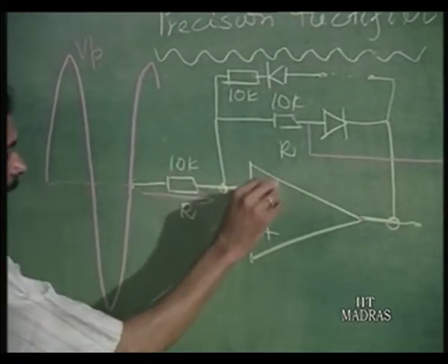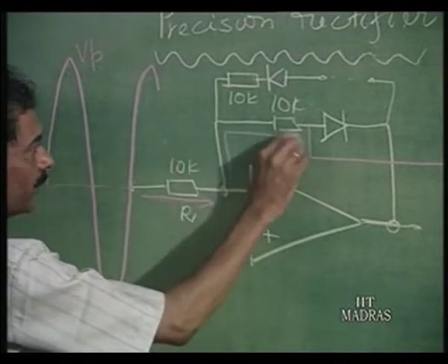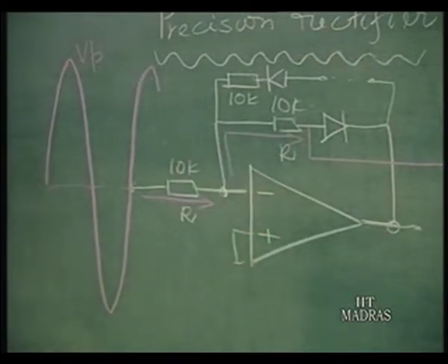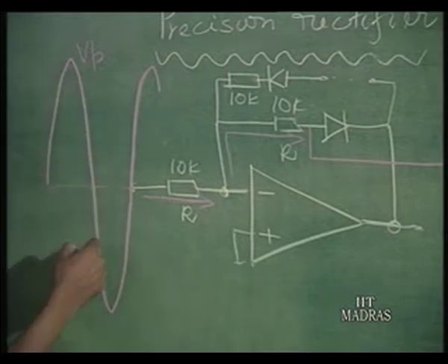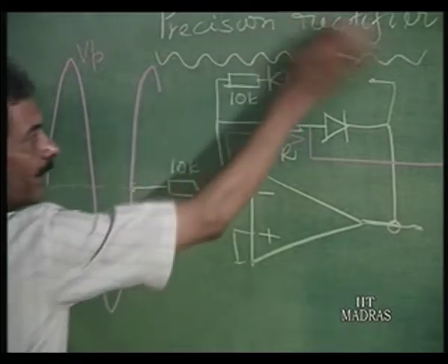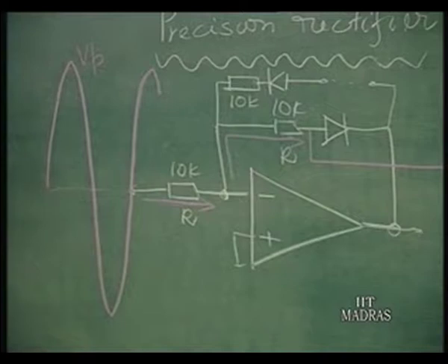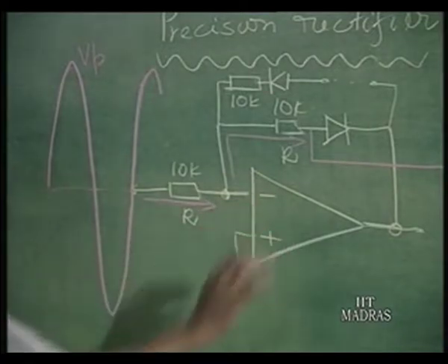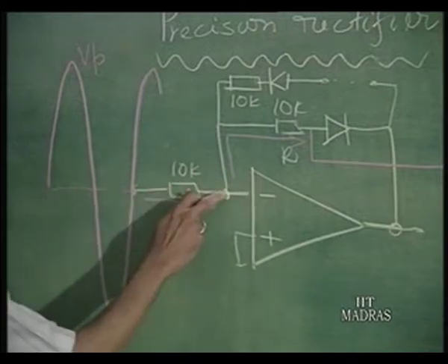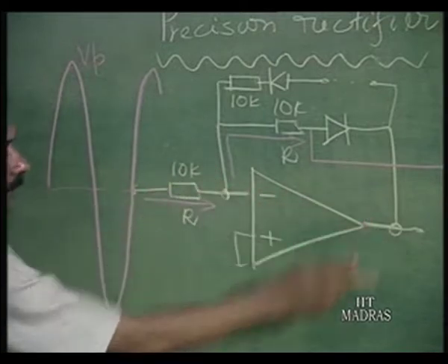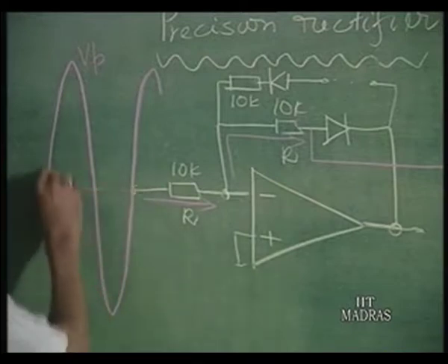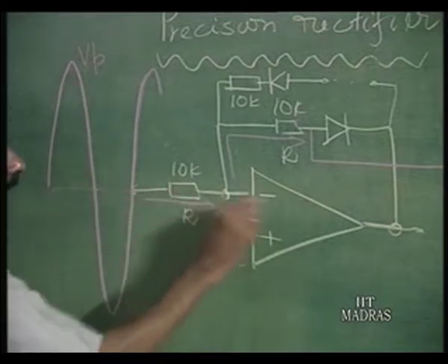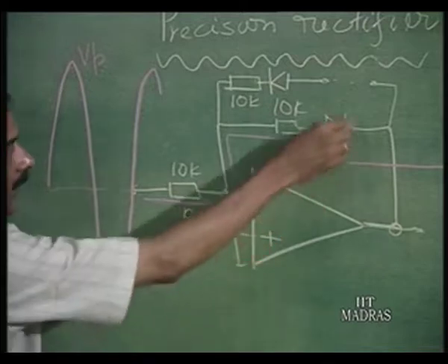But on the output side, this V I by 10 k is pumped into this diode, okay, when it is going positive, and if you do not have anything else connected, right, then this path is eliminated, and therefore, this current cannot go anywhere. Okay. So, the op amp is going to behave like a comparator there, where it will be simply magnifying whatever voltage is appearing here at this point, but that is of no use, because this positive voltage is going to get converted into negative here, okay, and this diode is going to conduct.